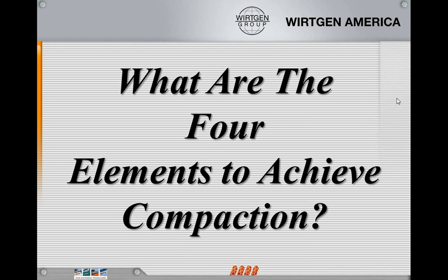We want to have good material that's going to be stable and give us a good load-bearing capacity, have some fractionation to it so that we have aggregate interlocking, and just make sure it's consistent, because if we have any kind of segregation, we're going to run across the same issues we have on hot mix.